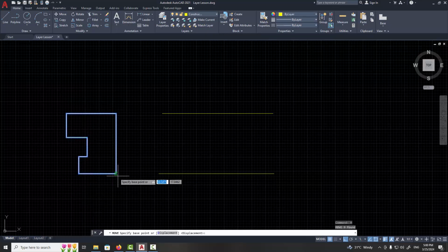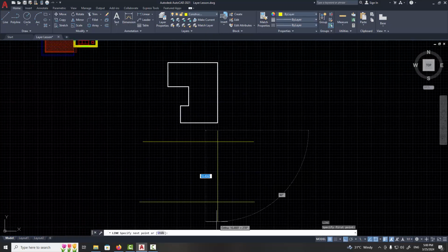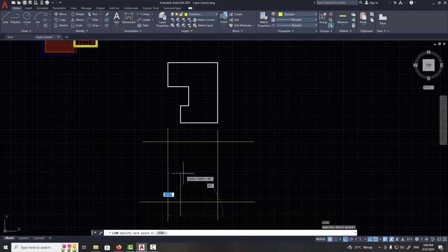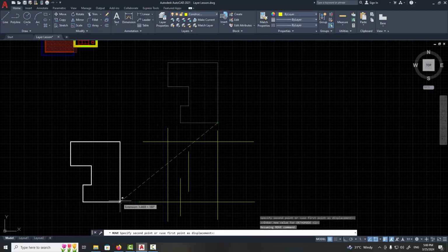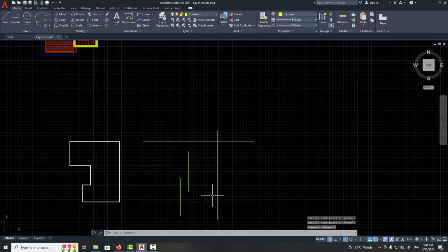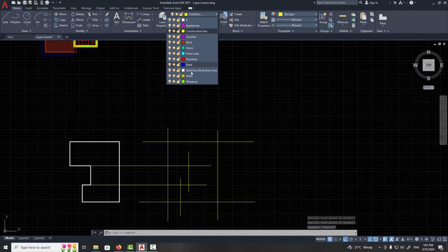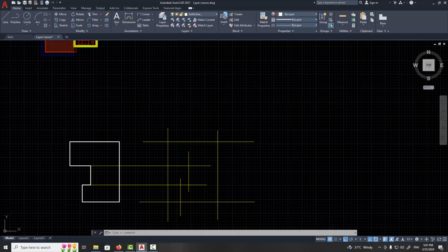Take a look at how I use construction lines to transfer the shape and how I move the object to take each side accordingly. Once construction line work is done, choose from the drop-down menu the second layer we created, which is solid line, and trace the shape as we did for the first object.